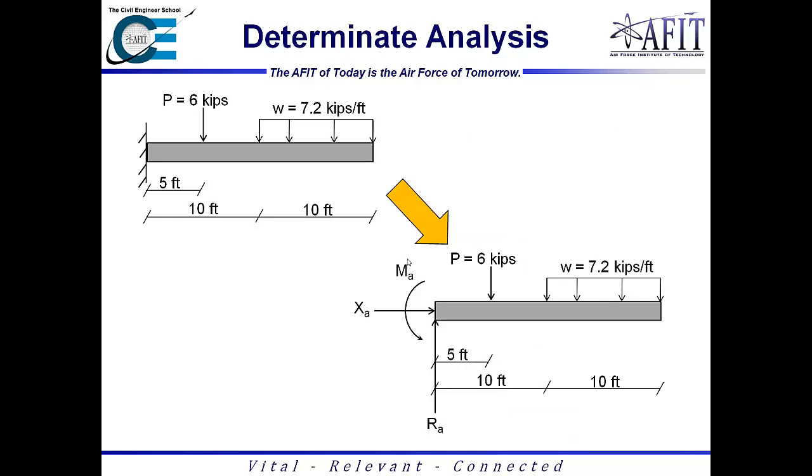And so taking this into another example, using a cantilevered section for determinate analysis. With a cantilevered beam with only a fixed support on the left or the right, this becomes a determinate analysis because once again I have 3 equations and 3 unknowns. And so resolving this into the actual free body diagram you see below, we go ahead and put all the reactions into the positive sign convention.